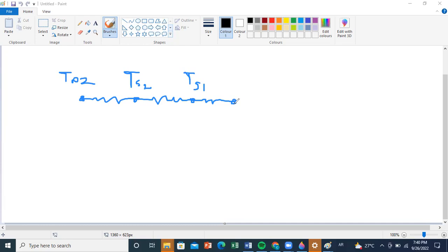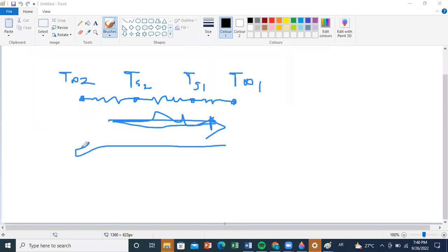And this is T infinity 1. Okay. And look, it depends which one is larger to know how the flux is moving. So if T infinity 2 is larger than T infinity 1, your flux will be in this way. If we are working in the opposite way, so if T infinity 1 is larger than T infinity 2, then you can know that your flux will be moving in this direction.